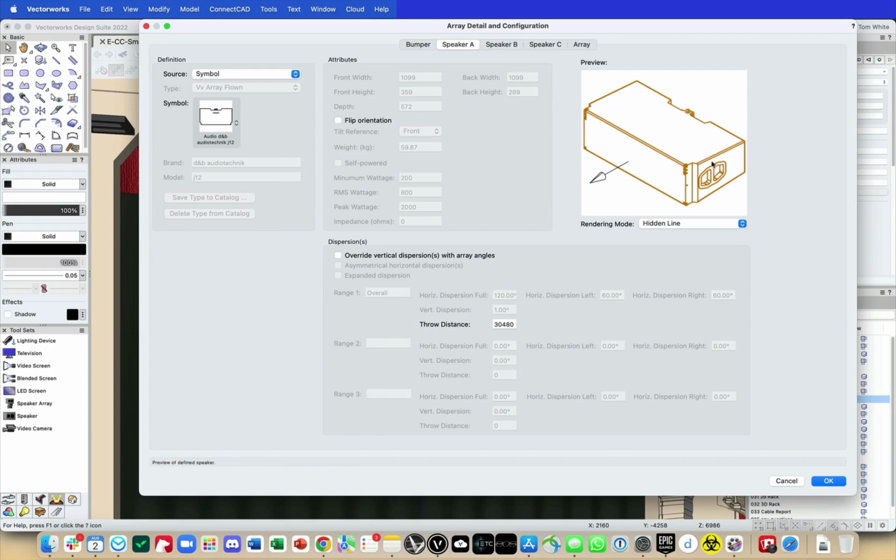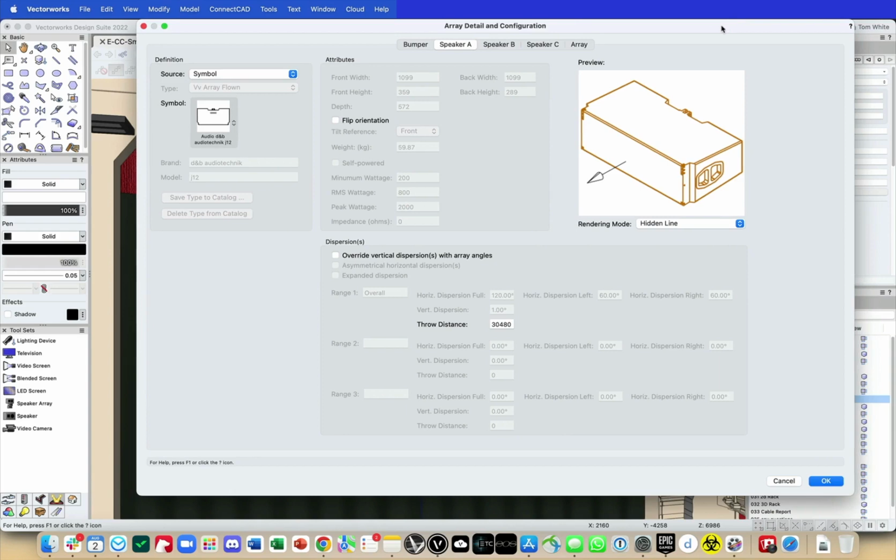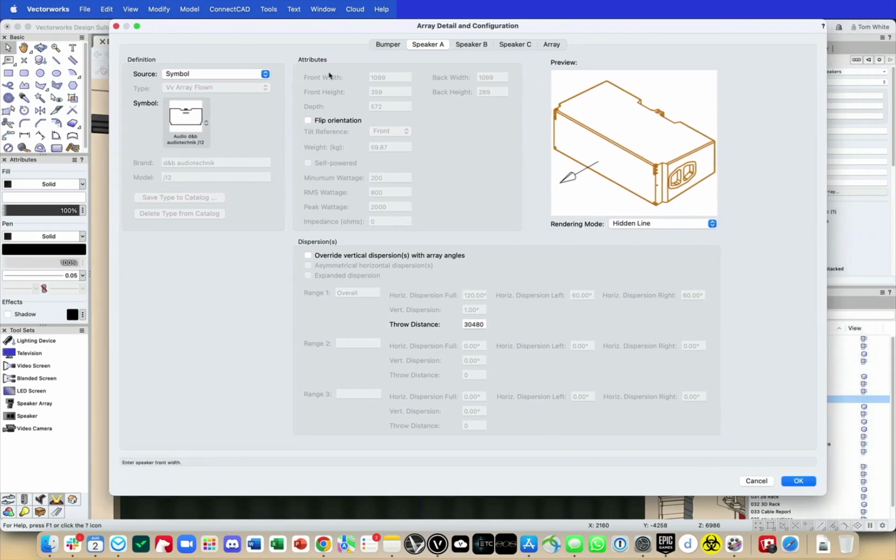What you'll see here is that we have slightly more complex geometry, and for this particular project, it doesn't really matter too much, to be totally honest with you. If I had a massive arena and upwards of, I don't know, 150 boxes of J, then I would probably regret that at some point, depending on the machine I was using. Essentially, the more efficient geometry can be found within the catalog items versus the manufacturer's detailed symbols. For small to medium projects, this is fine. For really big projects, you need to ask yourself, do I need that information?